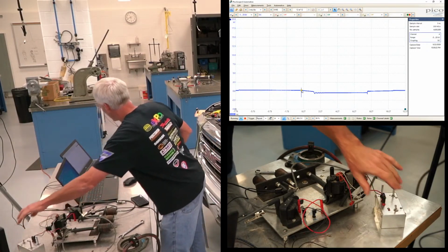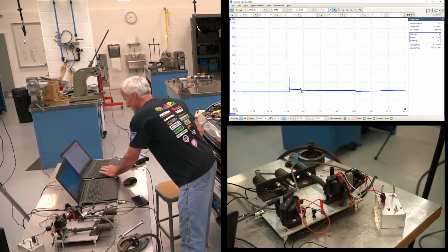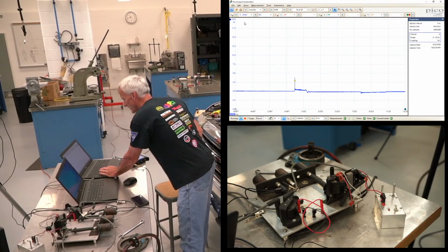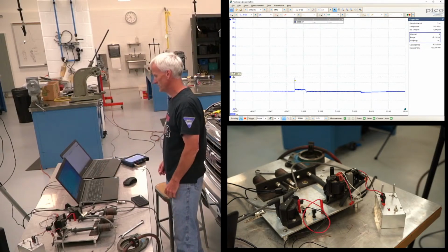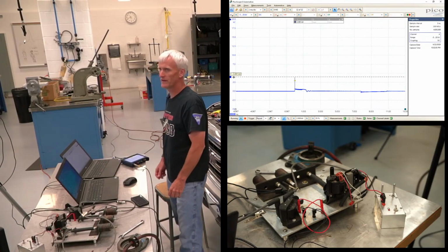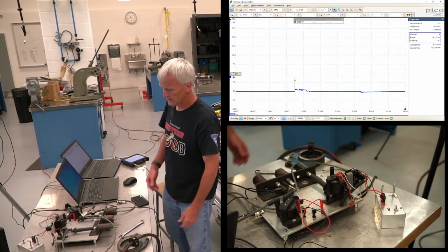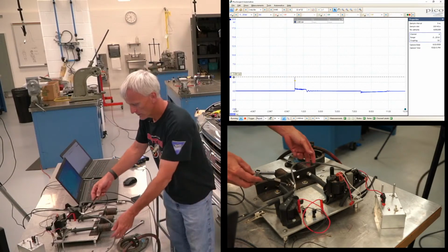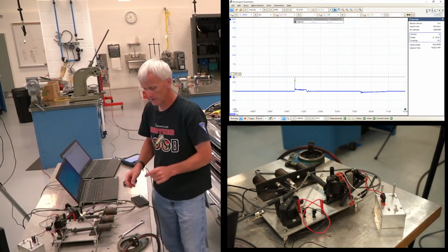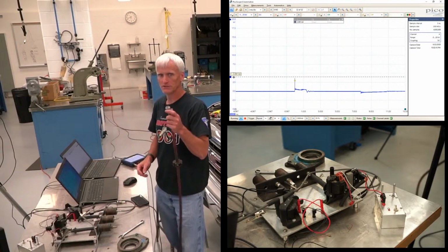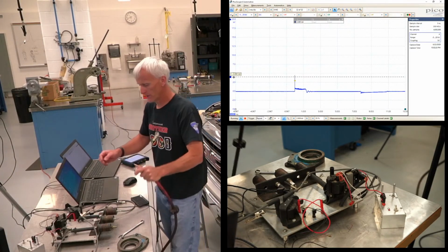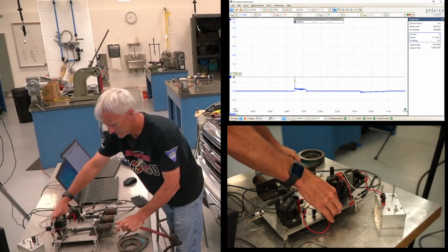So if I go ahead and fire this back up, move my trigger back up to a spot where it stabilizes, you can see right now, firing into open air, that coil's pretty much taking almost 4,000 volts. Not that much. And it is firing both plugs, but I am only measuring the one that's going into this cylinder right here. So now I've got an air hose here, and I don't know what the air pressure is hooked up at, but I'm going to go ahead and plug this in and just take a look at what happens.